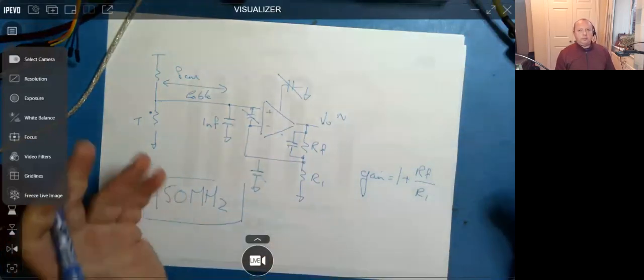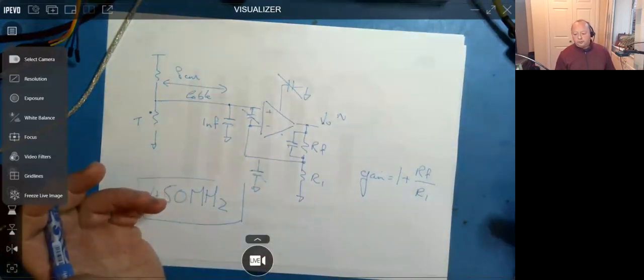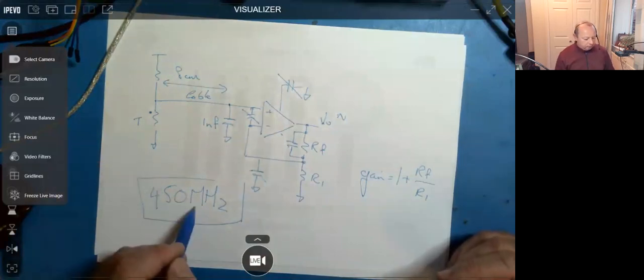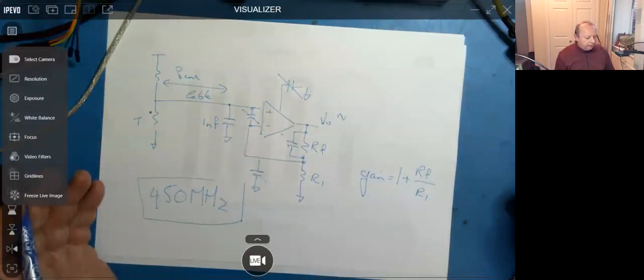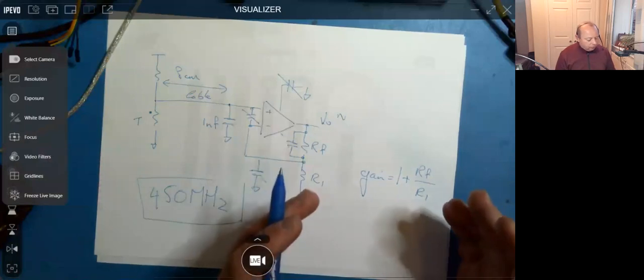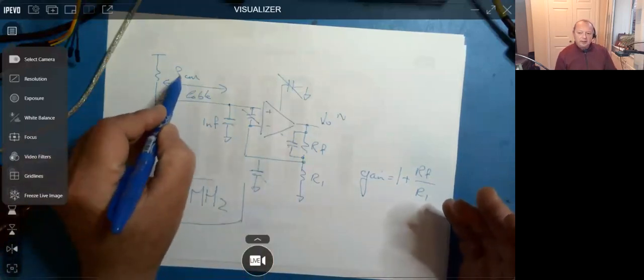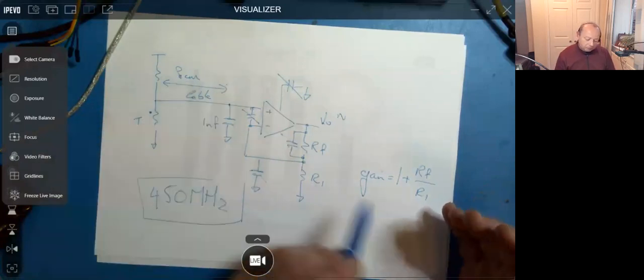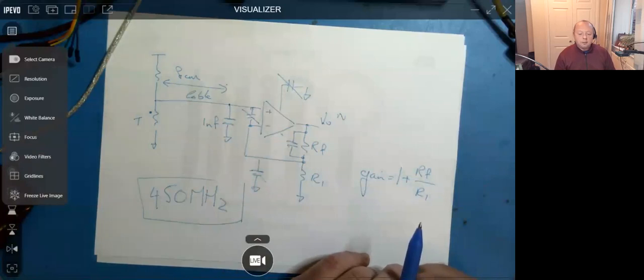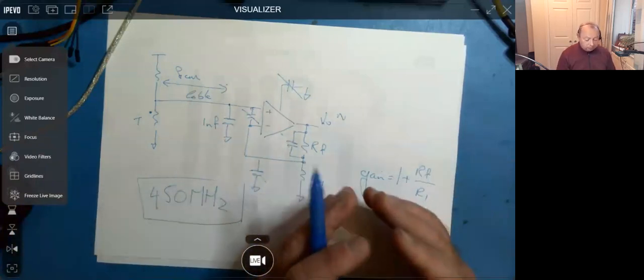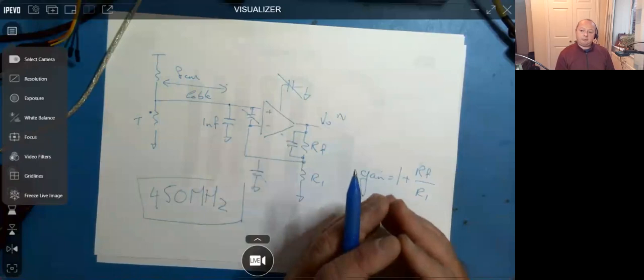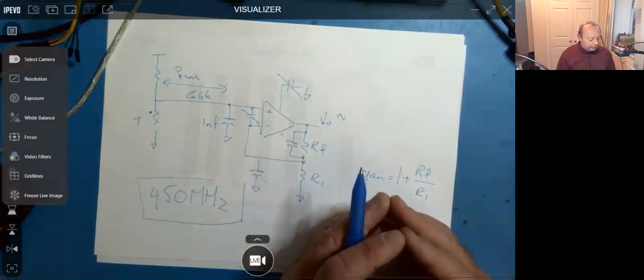But of course, you can have problems up to the 16th harmonic of a frequency. So if you took the wavelength of 450 megahertz, took a, is it quarter wavelength? Or half wavelength, the quarter wavelength, isn't it? You can take that, and then if you divide that by 16, will you start to see a 16th harmonic come through the cable? Maybe. I didn't actually calculate that, but yeah, cable lengths, all sorts. And of course, as electronics get smaller and smaller in battery, I'm told at the EMC test site, they're starting to see more and more problems with battery operated products at really high frequencies. So there you go, word to the wise.